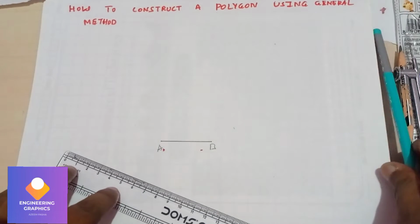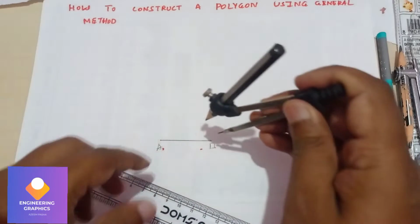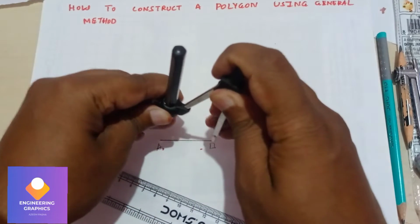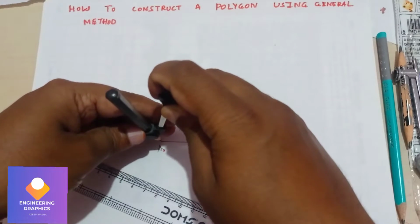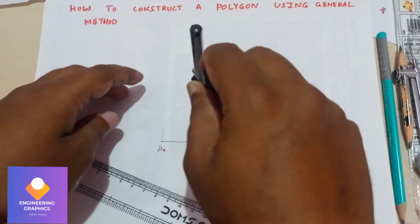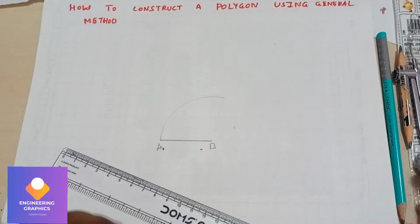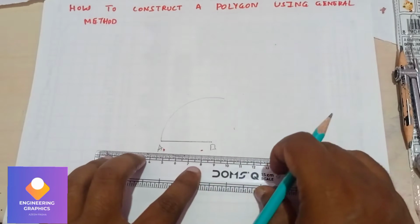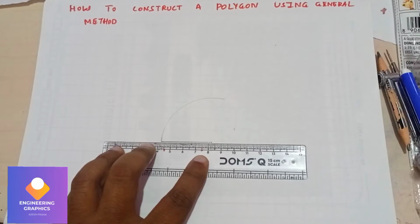Now take the compass and draw an arc here. I'll be following the same procedure we did for the remaining polygons. The same method we need to follow here. Measure the 40 and draw an arc. Now draw a perpendicular line here.